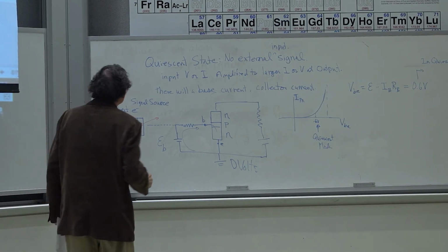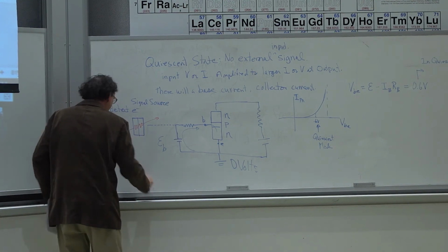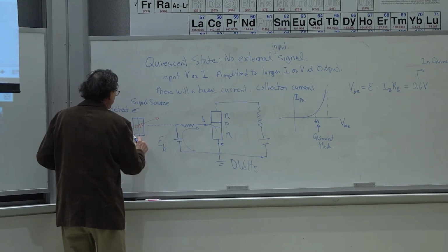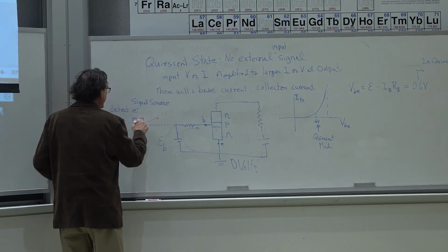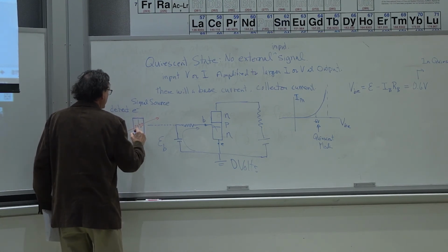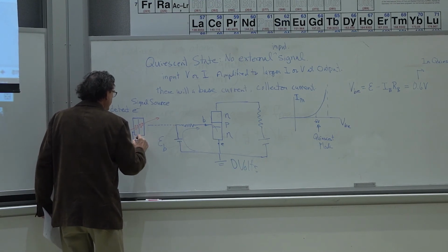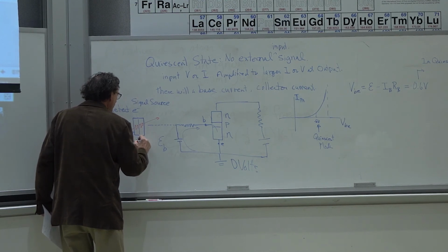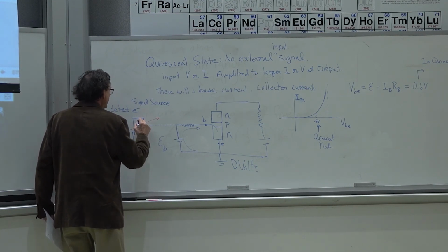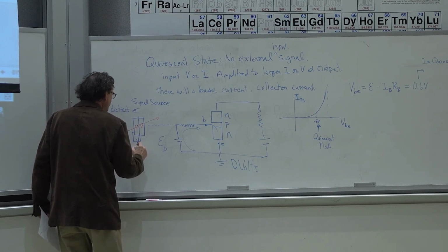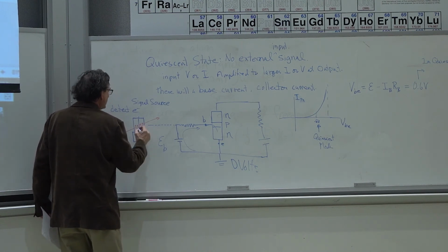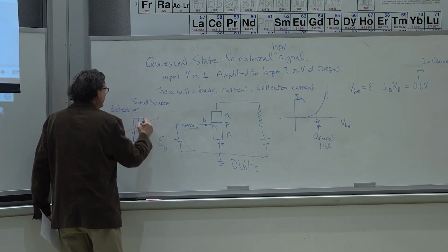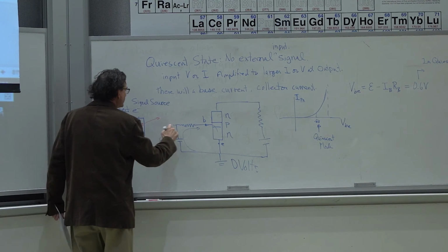So it's an ionization. As a result, I now apply a voltage between what we call the cathode and the anode. So this outer can will be at negative potential with respect to the center right here. And I'll put a high voltage so that I can collect the electrons onto the wire. Right? So the electrons are collected onto the wire.